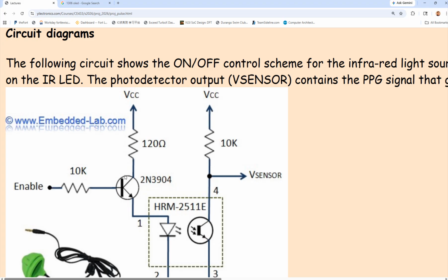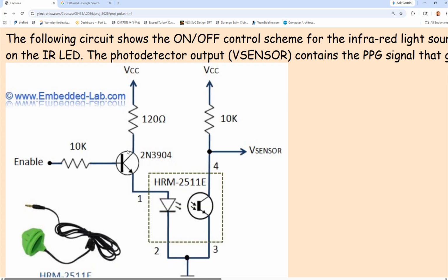It's an emitter. So the BJT is just performing as a switch, right? You give a voltage on, you turn it on, and that's the base resistor, and it's giving you a little base current, and that base current is being amplified by the collector emitter current, and you don't want this to be high, right? This is only a current limiting resistor. It's a current limiting resistor.